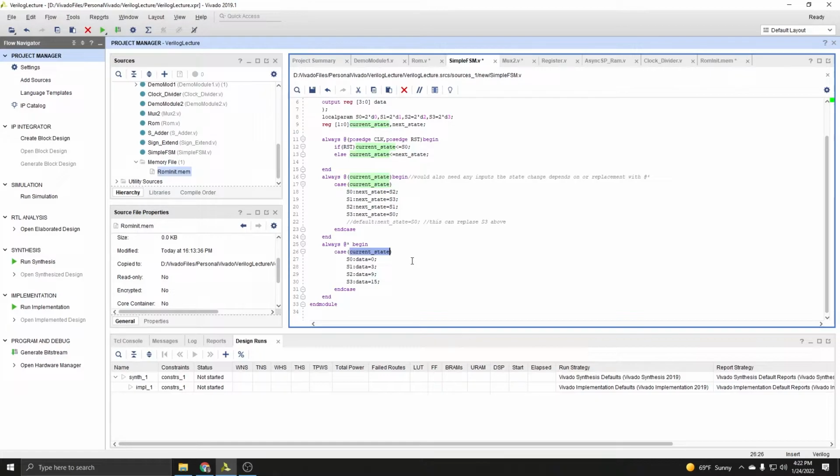So at star is basically true combinational, and then the at above is combinational, but you only want it to be sensitive to the signals that you provide. For example, if you had several signals that changed the output, but you only wanted the output to change if one or two signals change, then you could choose them specifically.